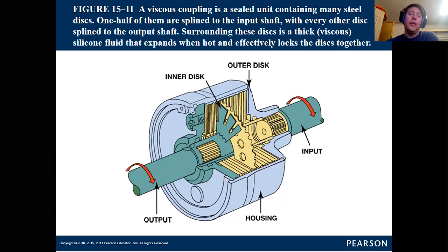What they're doing is they're incorporating a transaxle on the front wheels that has a power takeoff. It's the best way to put it. It's a power takeoff, so it's another drive shaft that comes off of the transaxle and heads in a straight line towards the rear axle, but between them is a viscous coupling device like this illustration in front of us.